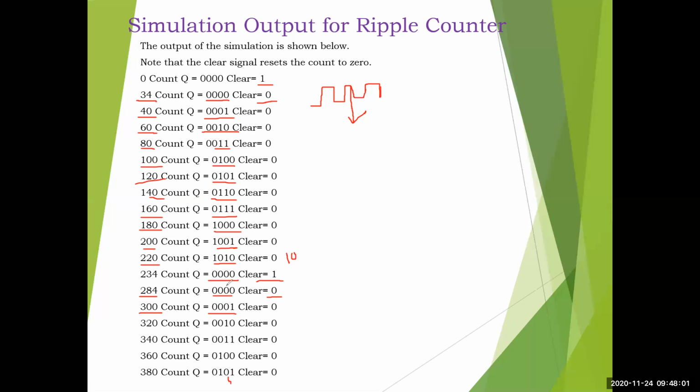Just to show you this idea, this waveform was shown. And at 400 time units, it is not written, right? Up to 380 it will count. At 400 it is finished. That's why the last value was 380. At the 400 negative edge it will stop, so that is not shown here, because it is not going to do anything, it is stopped. So the waveform is not coming.